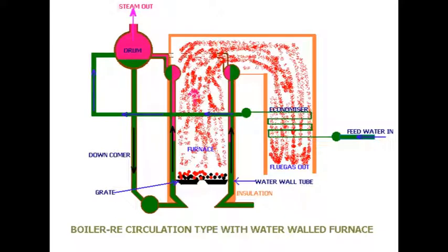In the next phase of water tube boiler development, it was observed that the quantity of steam generated by the heat absorbed in the bank tubes and the amount of heat wasted is significant. Therefore, to minimize this heat waste, the concept of water walling of the furnace came up, and gradually from the bi-drum we came up with the concept of a single drum or steam drum.